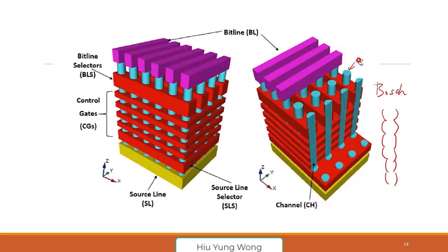So they have very good chemistry control, first on the temperature. The wafer temperature is important, as are the etching chemistry and passivation. When you etch something, the chemistry is going to depassivate, then passivate to prevent further etching. You need to go through all this process to make it nice, then it works well.